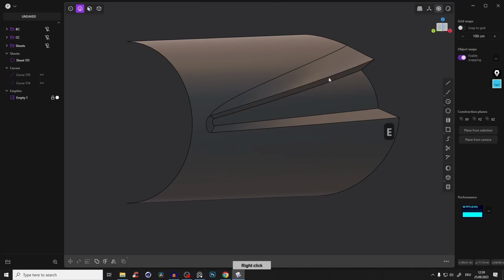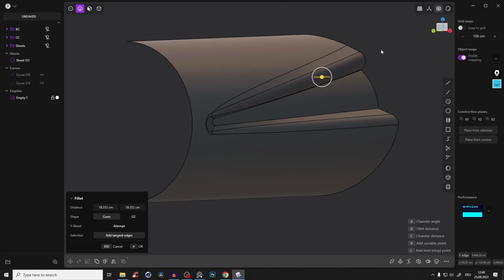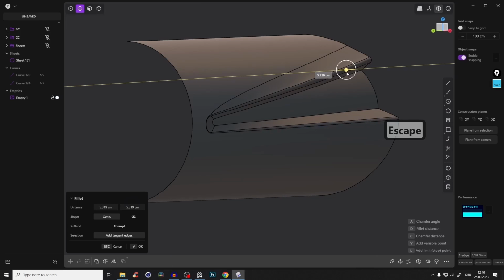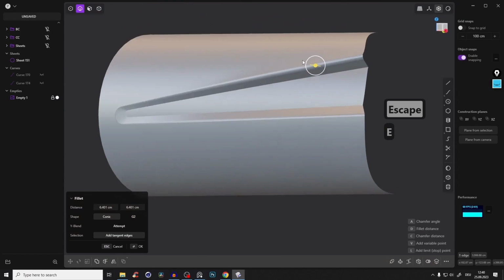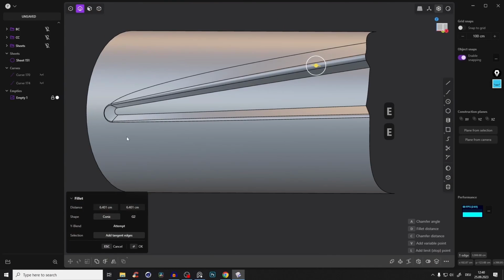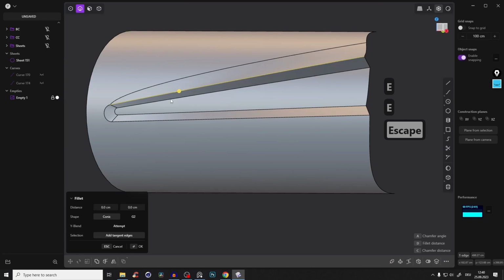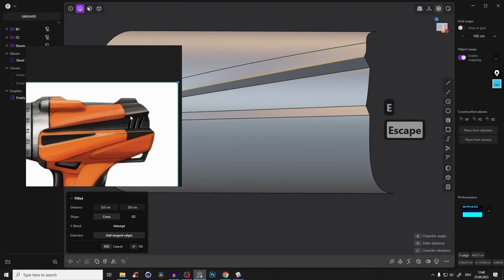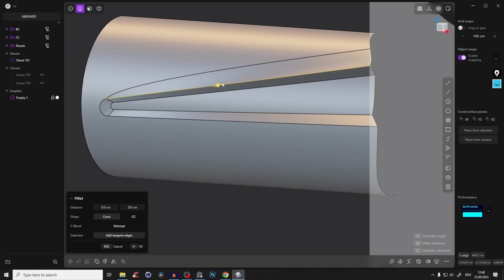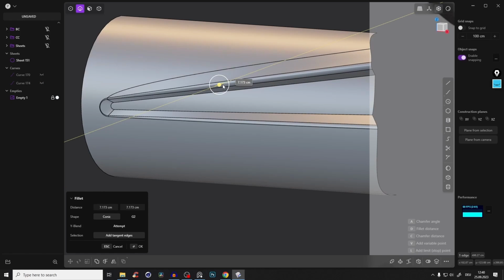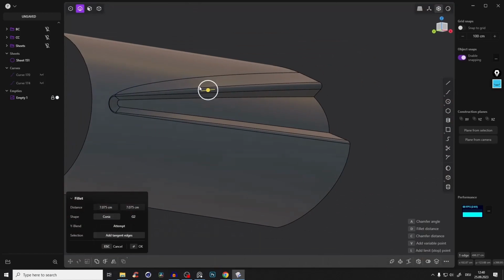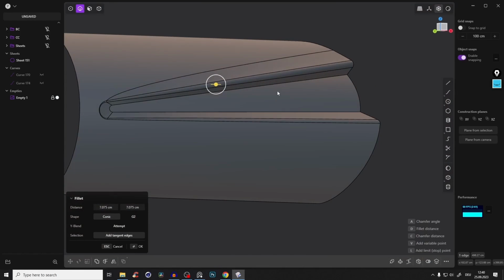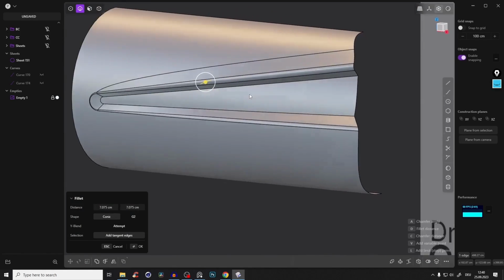So now we can try to give it a, how's it called? A fillet. And in this example, you see it works really, really good because we worked very clean. So we don't have to pipe it here, because what we want is that those fillets on the edge are getting maybe a little bit bigger than on those ones. If this wouldn't be possible, then we would have to pipe it again and rebuild all of those edges, what we did in the two previous models.